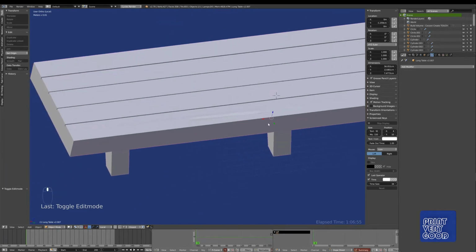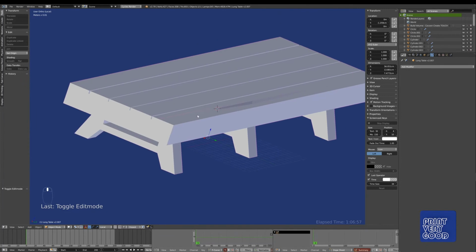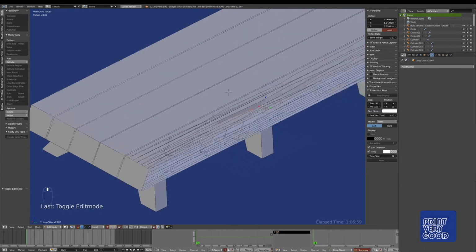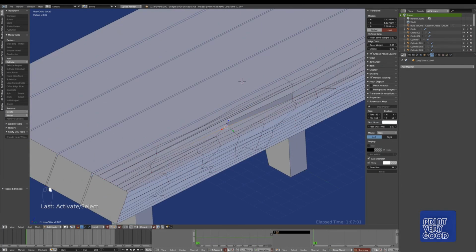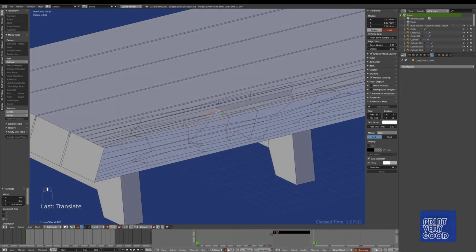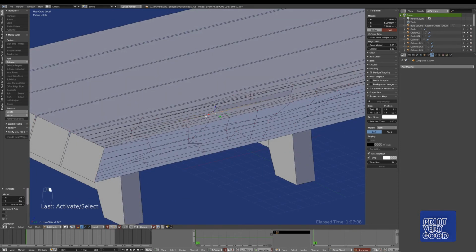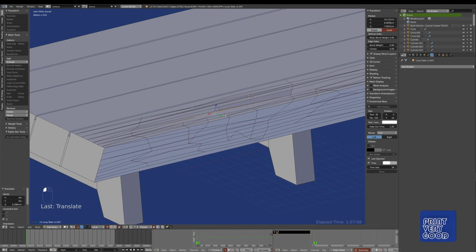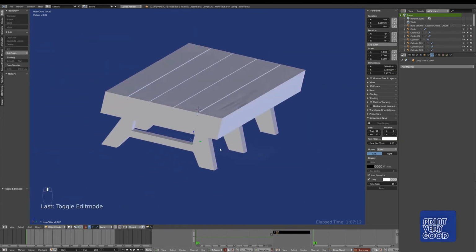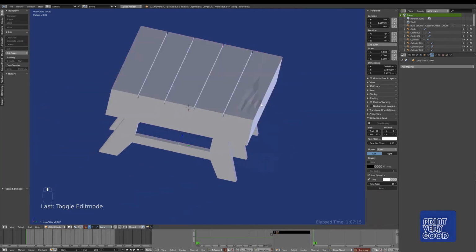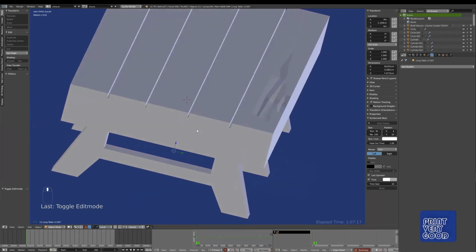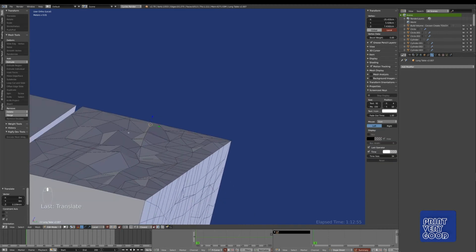Once we have some geometry in there, we can actually start picking up a few vertices here and there to give us the look and feel of timber and timber grain. The purpose of modelling in this way, instead of doing a displacement map, may be that you are looking to get a more toony style of wood grain into your model rather than a realistic displacement map look. And this is just a good way to add some geometry into models quickly.